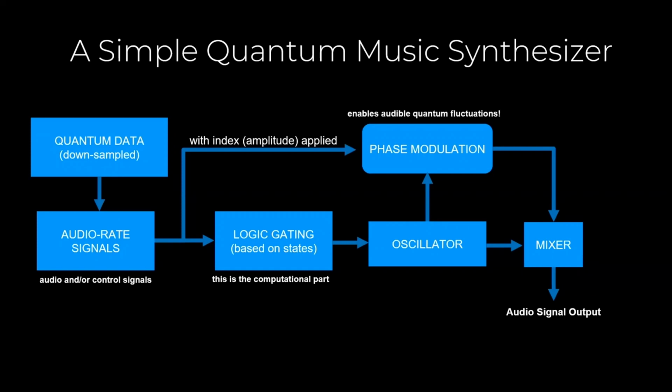In our system, we used Max for Live. At first we tried the native library with the gate signal object, and it had all kinds of sampling errors. So we switched to gen~ objects with gate, which worked perfectly. Maybe just a word of advice: that's a really good way to go when you're doing signal processing, because the gen~ objects are basically C subroutines, so they're very efficient and accurate.